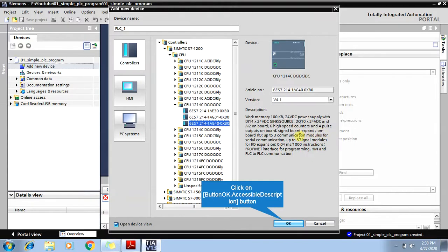Apart from that, I have 4 pulse outputs. Pulse outputs mean that if I want to connect this PLC and drive a stepper motor or a servo motor, then this CPU has the facility of giving you outputs in pulse form. As you all know, servo works on pulses and stepper also works on pulses. So this can be given by this PLC. So such type of 4 PTOs are available.